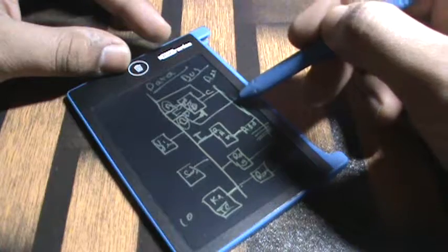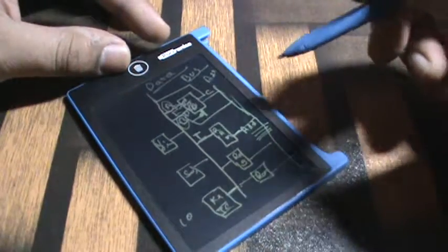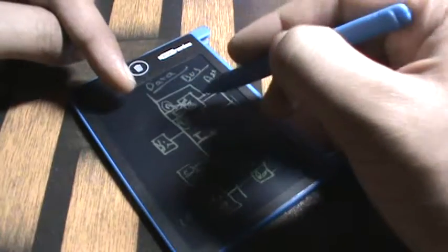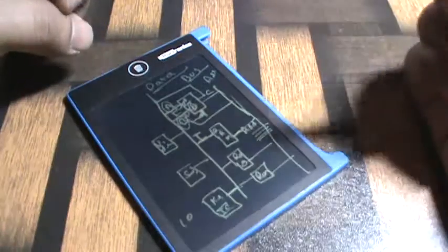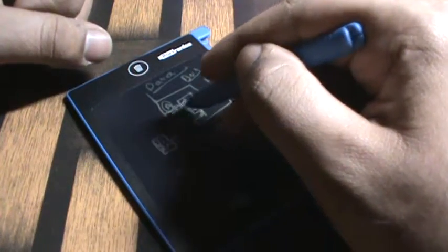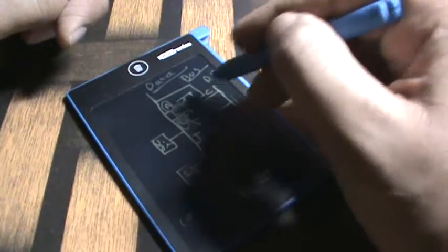It is going to set some value on our address bus, which connects to the OR gates of each and every component, and these OR gates become true when the particular address line connected to that OR gate becomes 1.